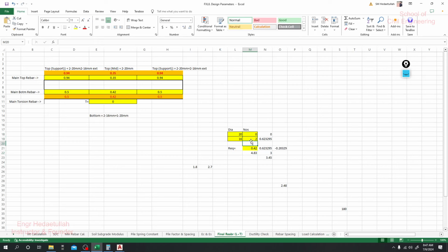If we provide 2 16 mm bars, we are providing 0.62. That is the maximum. I mean we are providing 0.2 more than our required value. So it's okay, because less than 16 mm we cannot use, or it shouldn't be used actually. So 16 mm 2 bar is done, and if we provide that, it will be okay, because it will cover our whole beam.